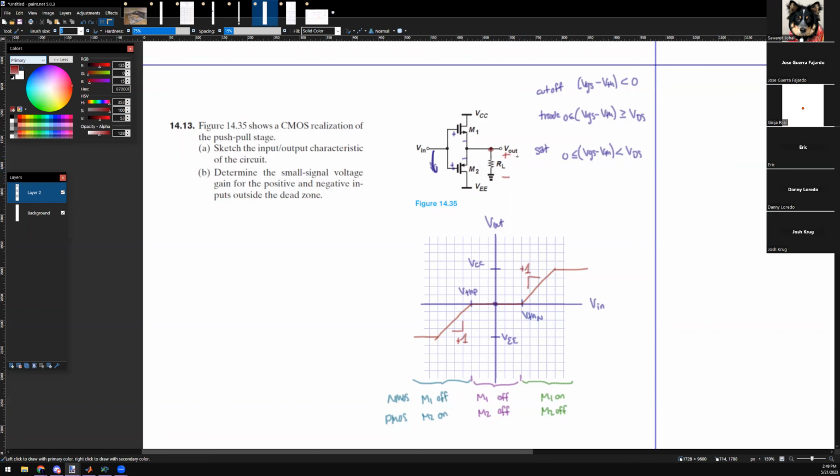0 amps, because V out is 0. There's no current flowing. And isn't that beautiful? Because what does that mean when you're not playing music? It means you're drawing no power. Right. This type of stage is also a very efficient power amplifier.